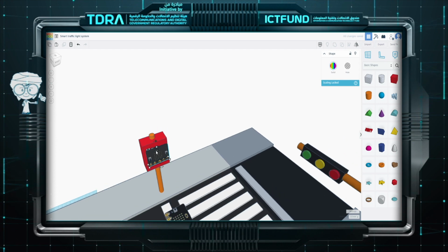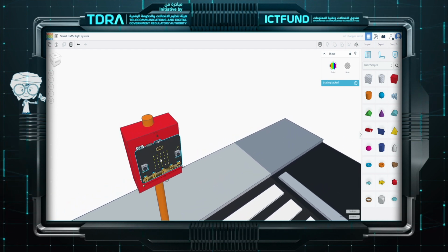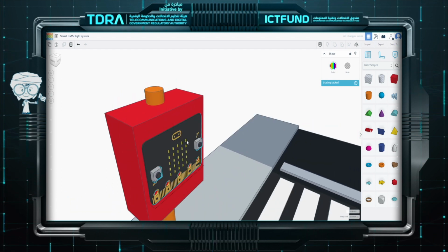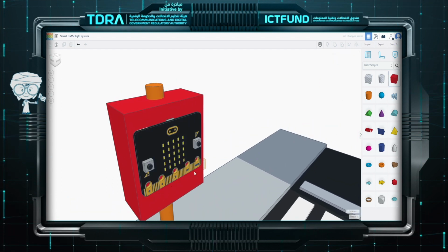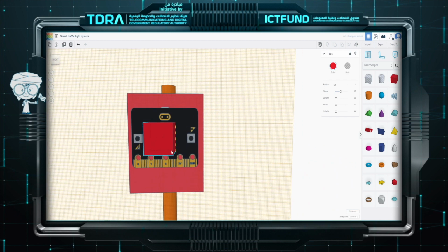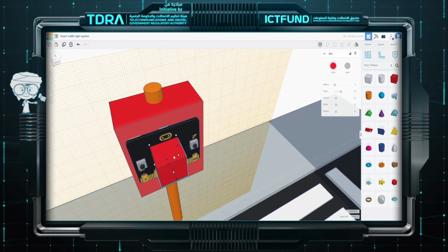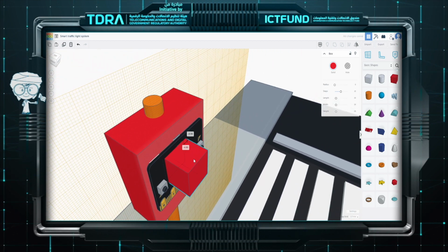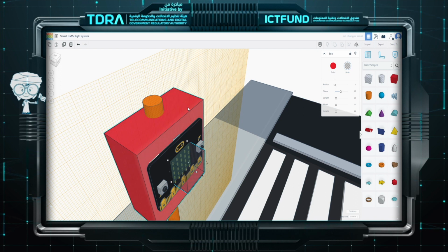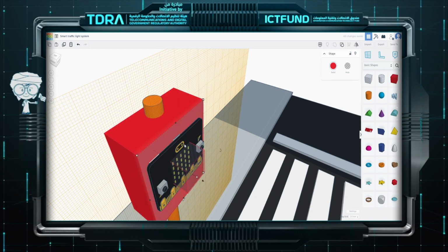Here, we're gonna make a hole for it. Okay, sounds good. Let's make a hole only for the light. Let's say the work plane, put it here, and make a hole only for the light. So it's gonna be here. Push it inside. Cannot push it inside yet. And then hole. Shift select the other part and group them together.